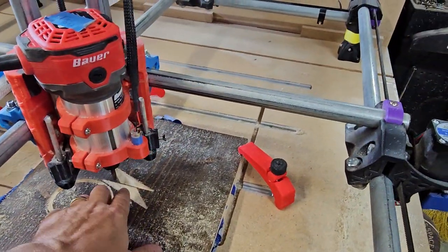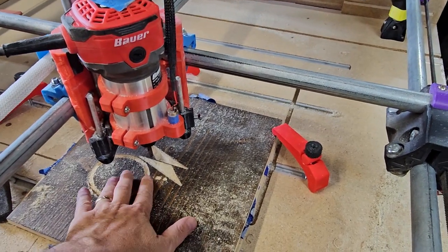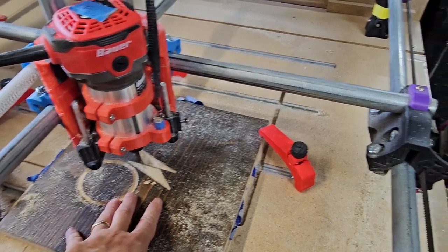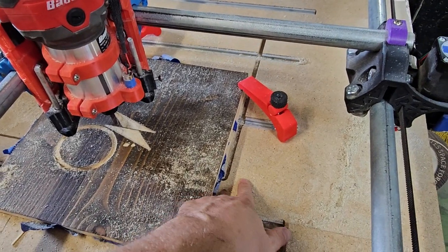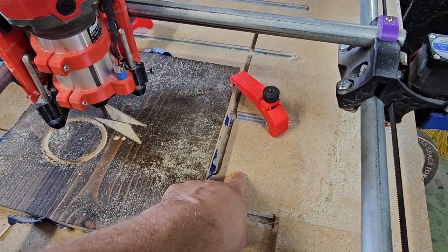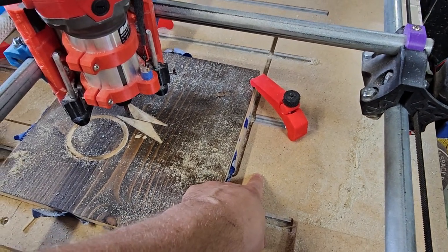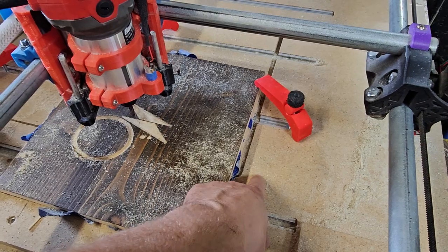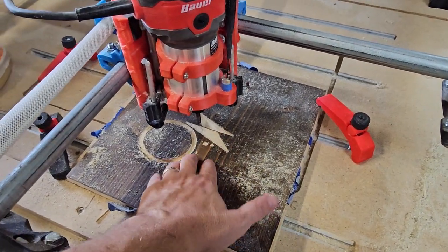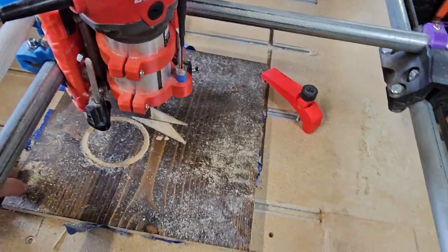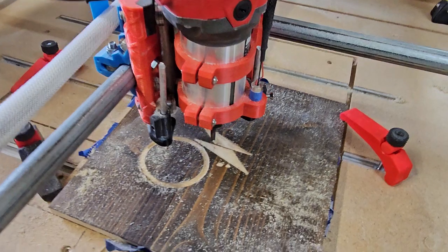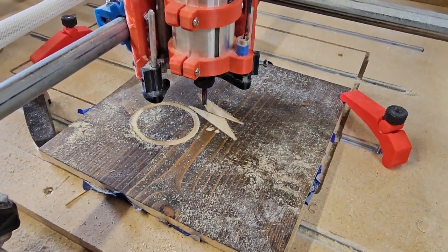Now we've got to set the Z, because we're doing everything by depth. We have to tell the machine where is the surface of this. And there's different ways to set Z. Some people will set their Z based on the table height, so they'll measure it to there. And you just have to set it up that way in the software when you generate your G-code, so it knows that you're measuring from here, not from here. Everything I'm doing, we're going to be measuring right from the surface of the board itself. So two different ways to do it, depending on how your machine is set up.